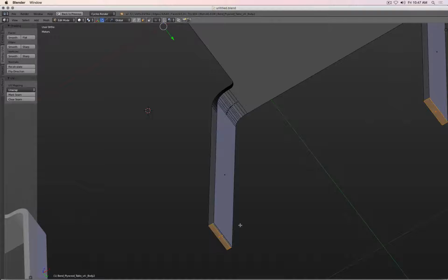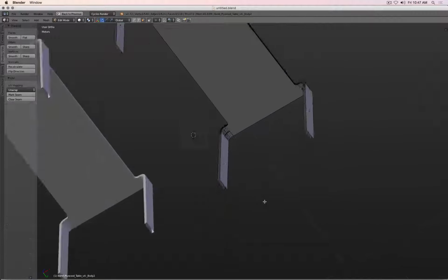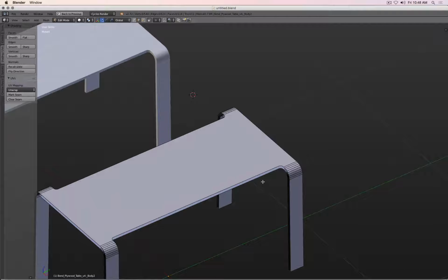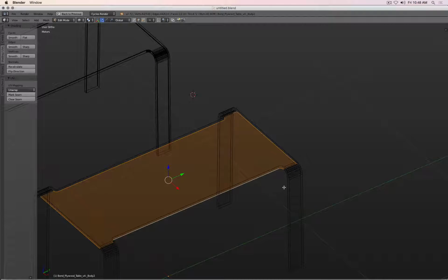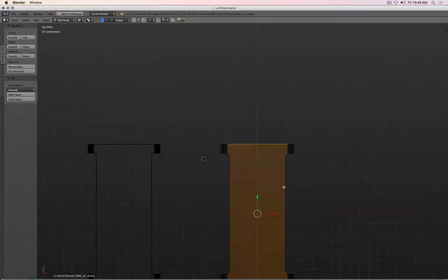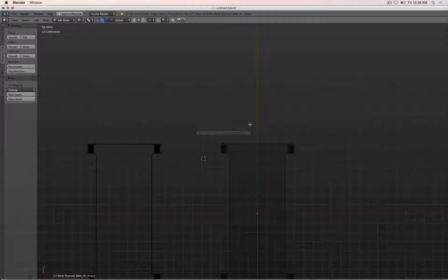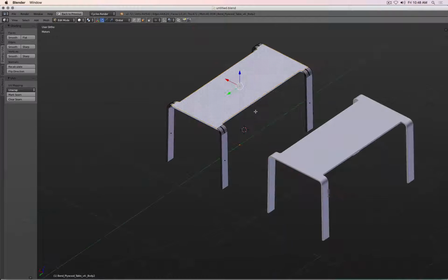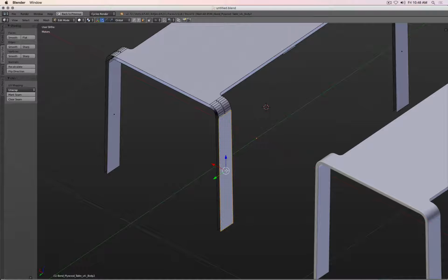So those I'm going to remove, delete face. So by having hidden those side faces, if you can do it, I can now actually go, for example, to a top view and, for example, select this one, and let's say press L. So, okay, click this one, press L, and there actually I see what's only linked together.